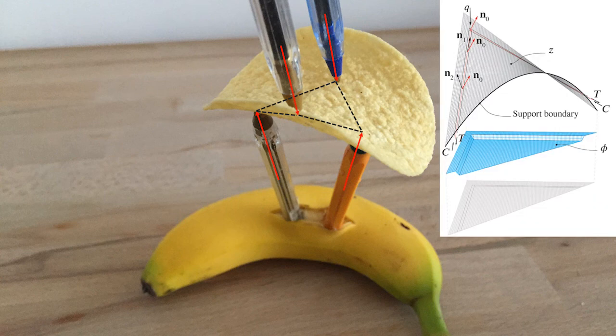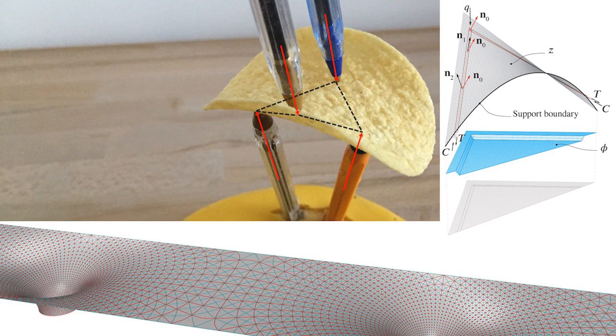With no other loads on the surface, the forces along the asymptotic curves are constant, but the slight difference in their direction effectively causes the force couple to form a moment. The asymptotic curves of the crisp are straight lines, so they diverge linearly and therefore the moment varies linearly. But in general, the asymptotic curves are not straight lines, so the moment will vary non-linearly. That is the case for the minimal surface we discussed earlier.